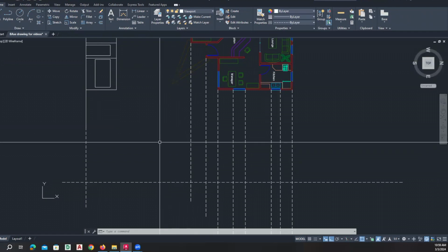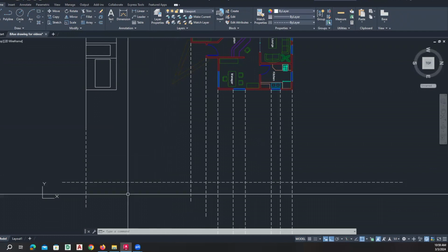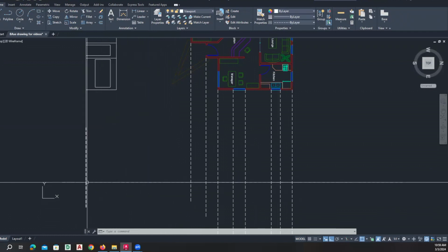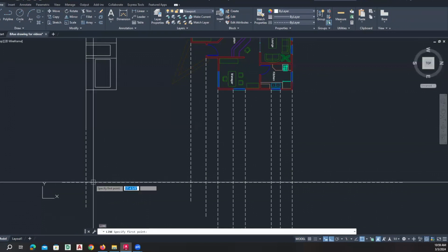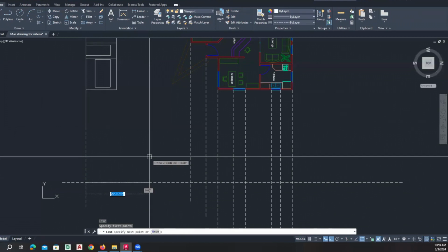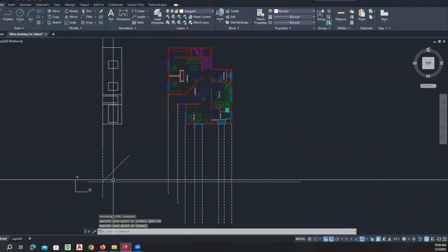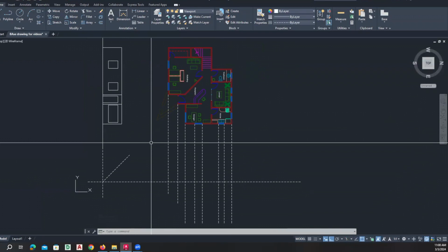If your drawing is a little bit more complicated and there's much more vertical information that we need to project and offset up from the ground plane, what might be easier is actually drawing a line from this intersection of the two ground planes at a 45-degree angle. And what that allows us to do, let's do that right now, from this line I will draw a line that is approximately 20 feet, direction 45. So now I draw a line that's 45 degrees from the intersection of this ground plane.